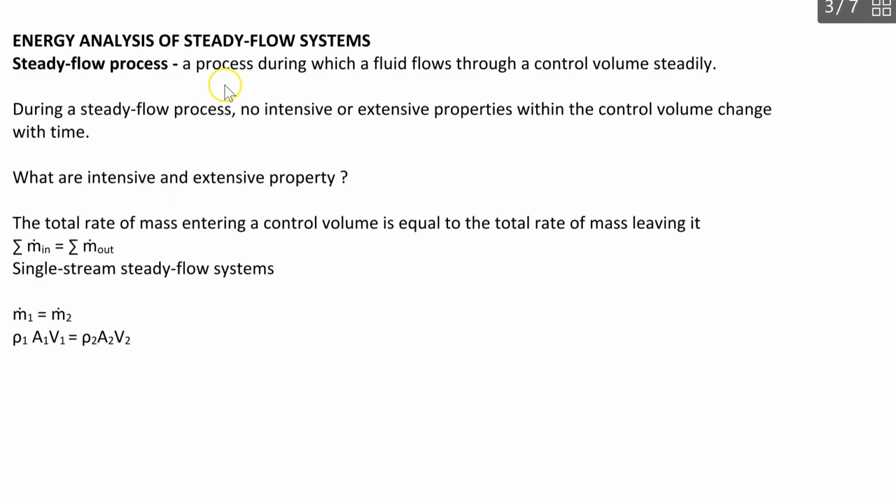Okay, there's something called a steady flow. A steady flow system is a system that doesn't change, and so theoretically the thing could run forever. And we're going to write mass equations and energy equations for these things. So, for example, whatever mass flows in, the rate at which it flows in is equal to the rate it flows out, because nothing is accumulating inside. And then there are these relationships, I'm sure you've seen these before, between mass and the density, area, and velocities. So these are mass terms, and the same thing up here.